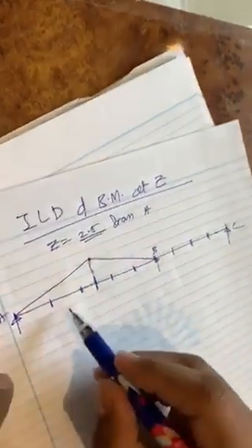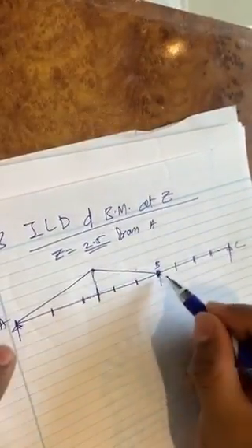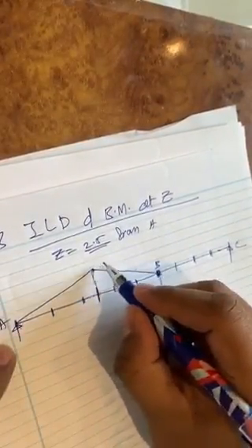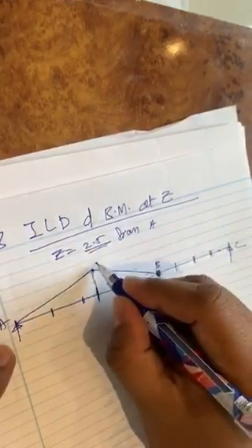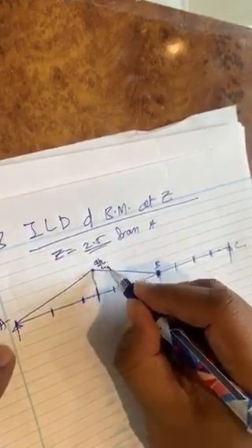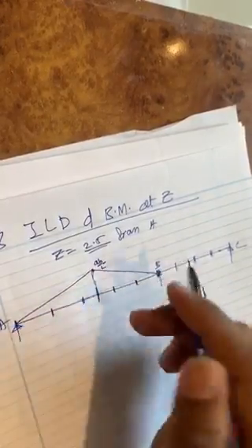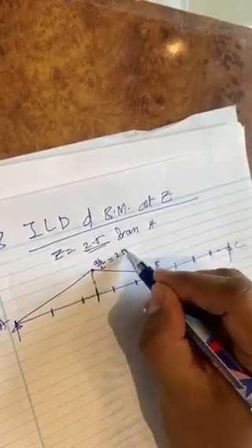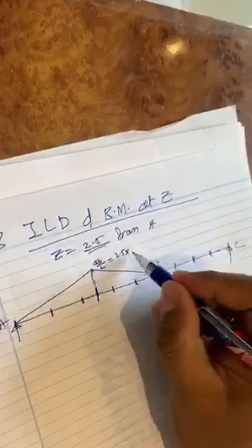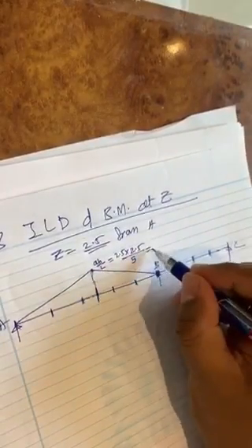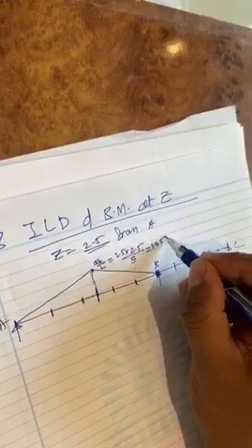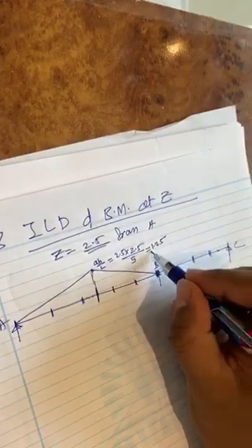And you know how to get the determinate ILD by providing a hinge here. So it is nothing but you can say A into B by L. So this value will be AB by L. So this side it is 2.5 into 2.5 divided by 5. So it will come out as 1.25 and then divided by EI.